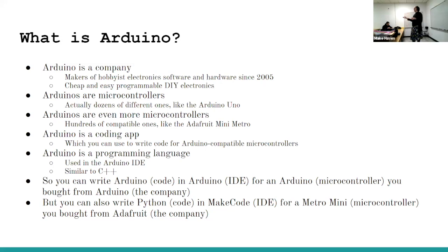So you wouldn't want to take a project like the one we want to build into a textile with a Raspberry Pi in it, because you would have to have a battery that's like 5 times bigger than if you use a microcontroller. Okay, gotcha. But if you want to watch a YouTube video on it, you probably want the Raspberry Pi. Yes. You're never ever going to do that on an Arduino. Okay. Done. Great. All right.